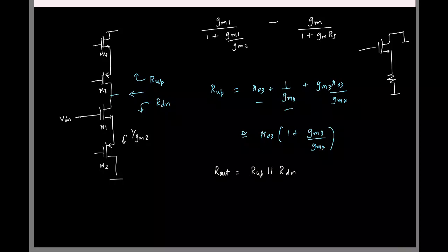Another thing I wanted to say is, you guys found R up and R down, but then some of you actually simplified the expression for the parallel combination of the resistors, and that's not needed. This is not a mathematical course. I'm not some sadistic mathematician who gets happiness in making you write 2 lines of long equations. For a circuit designer, this makes no sense. For a mathematician, this looks very good, like a nice rational polynomial. But for a designer, what makes more sense is R1 parallel R2, which gives you physical intuition of what is in the circuit. So if you don't need to simplify things, just keep it plain. It should be readable and understandable, that's all.